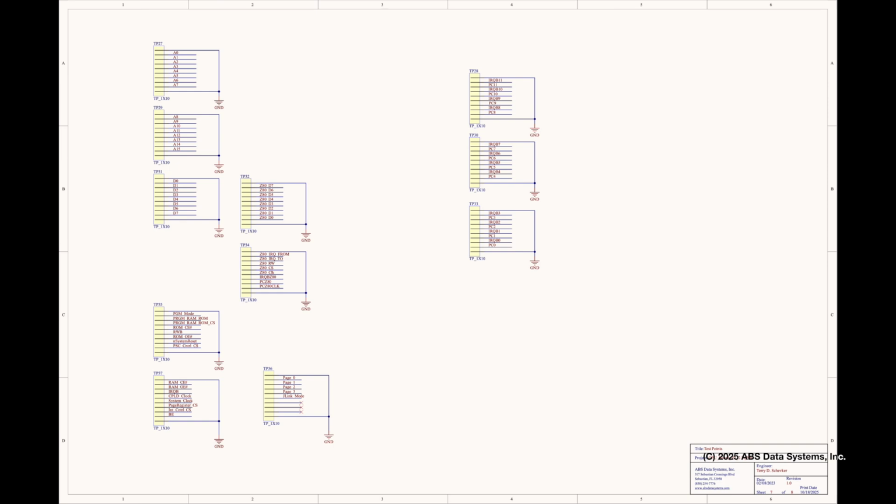Schematic page 7. One of my goals is to verify everything, as well as a way to capture the stream of data that the CPU is processing for debug purposes. All the test points on this page were designed to easily plug in my 64-channel logic analyzer. Since all these are test points, they could also be used to connect to other types of hardware expansion or other types of measuring equipment, even some modules.